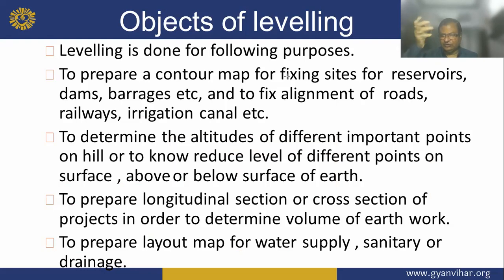What is the reduced level? Dear boy, if you find the level corresponding to a location, the ground level, that is called a reduced level. Suppose you are standing here. This is your dumpy level or auto level.